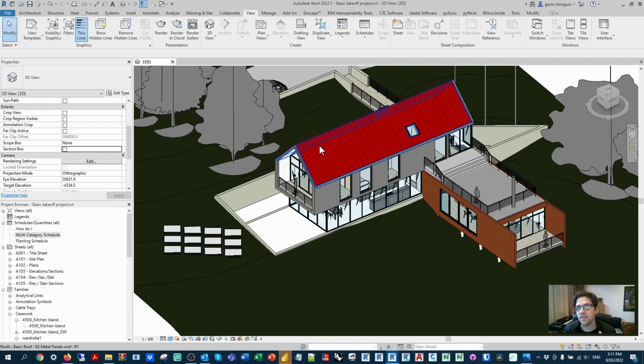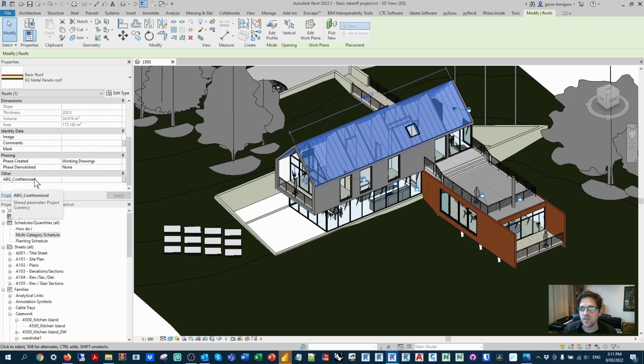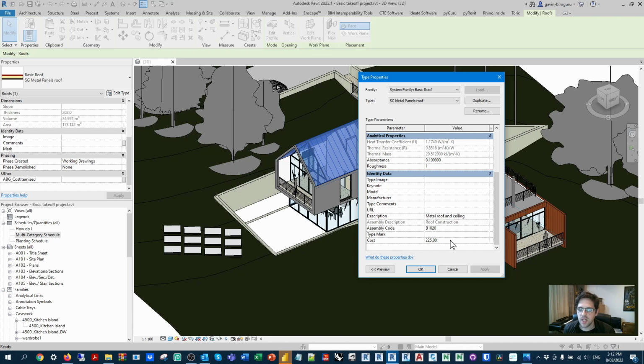If you haven't, I've already added some custom data to this model. For example, each object has an itemized cost instance parameter that we're going to generate, and this is going to be based on a relevant quantity times its cost, which in this case are type properties. So you might recall, if you have seen this, that I have populated them into cost groups, but as well as this, I've also informed them of the rate to use when they're measured by Revit. In this case, we're going to use Dynamo to use this rate to determine what the correct parameter is to read. Otherwise, we'll be using the cost and also associating a description. So you will need all of this data available in your model in order to undertake this exercise.